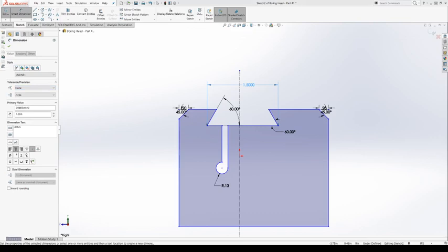But what about our tolerance? Well, again, we can add our tolerance here. So the advantage of doing this here is when we go to make a print, we can automatically populate the dimensions on the print. So if we make the dimensions correct here, even correct in so far as how they are toleranced, that can save us some time on the back end.